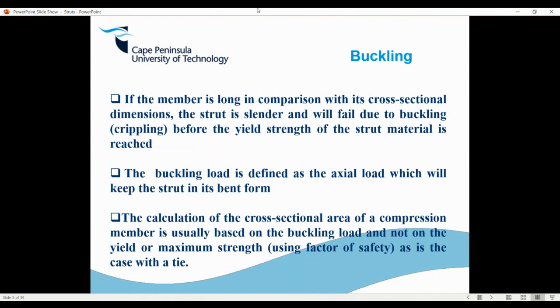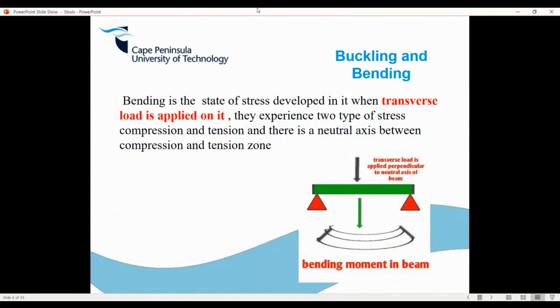I'm just reading a problem here, and I will definitely scan this in for you. It's a connecting rod for a slow vertical paraffin oil engine. It incorporates the stuff you learned in heat engines, and you're applying it here. So I will scan this and apply the same principles. Obviously, I've shown you that design. So if you have a column, one needs to be aware that anything in column form, you must check for buckling first, and then compression.